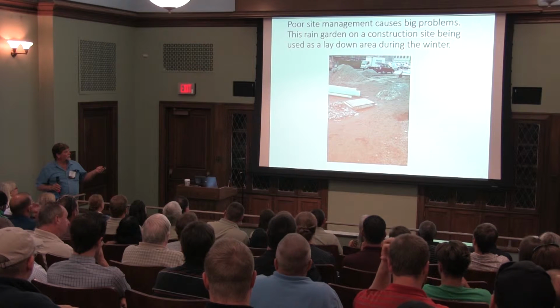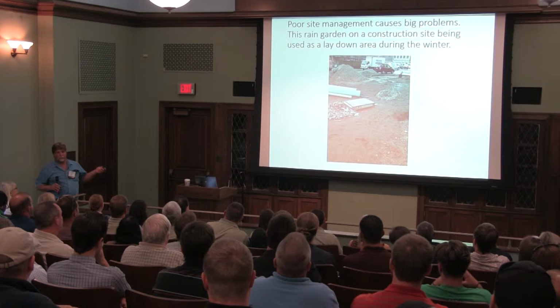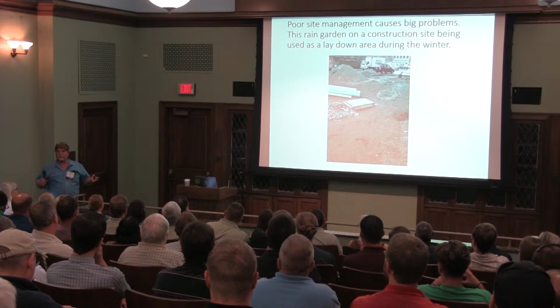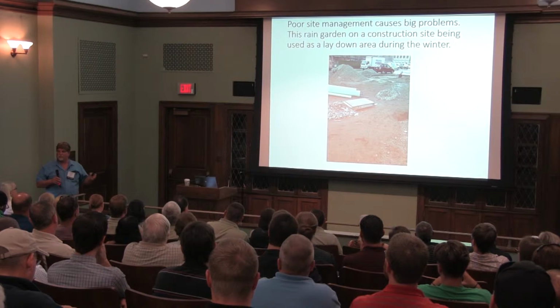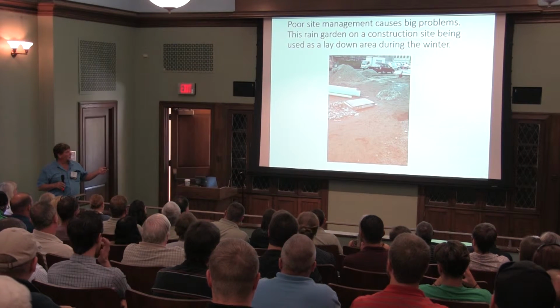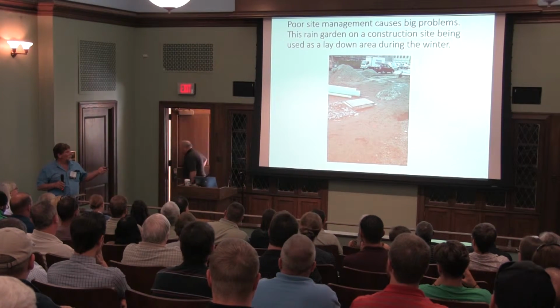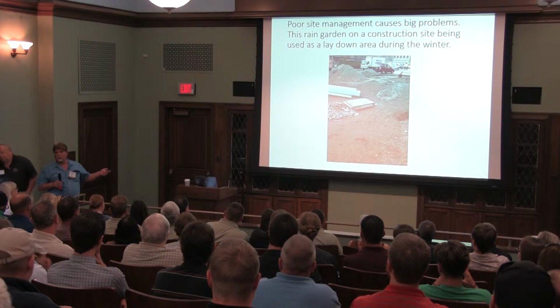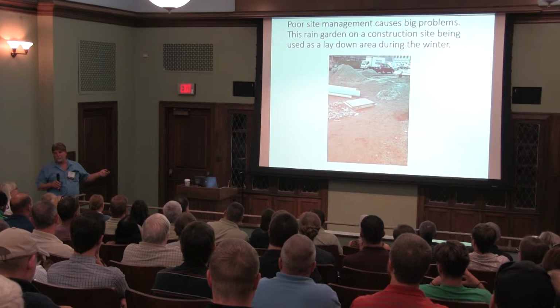Sequence of events, I always tell people, either get the paving done and then put the rain garden soils in, based on logistically how you get the trucks in, the triaxle trucks, big heavy trucks, so that you're not crushing the curbs and ruining the asphalt. Or you put this rain garden soil in just before you're putting the gravel and stone down for that parking lot.